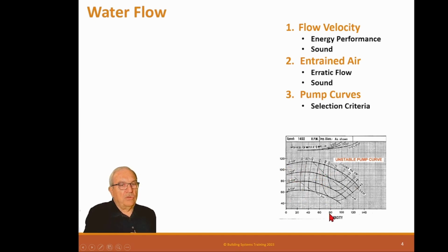So that means the chilled water system might have this flow, which I think right here is 80 GPM, might go down to 20 GPM, back and forth, back and forth. So we never want to select a pump that'll operate in this piece of the curve. If you have a curve that slopes back down, a pump should never ever be selected in that area.